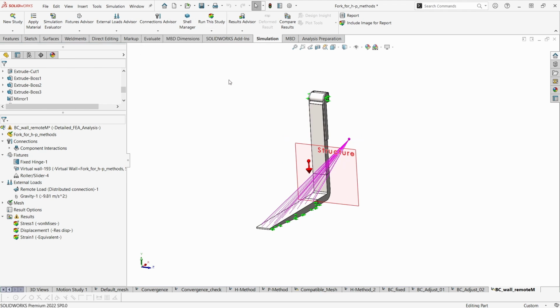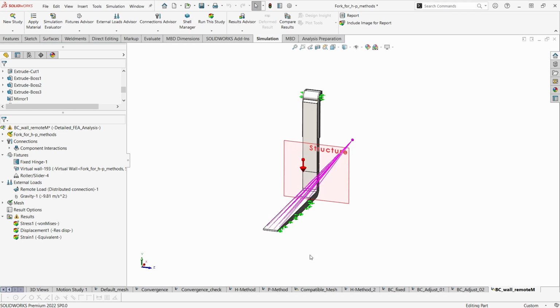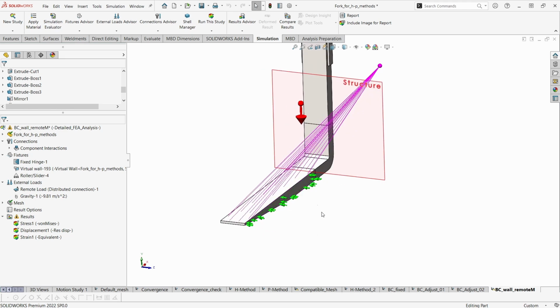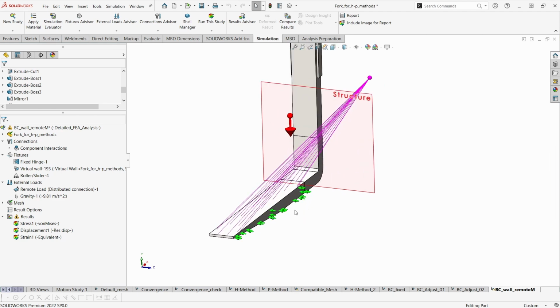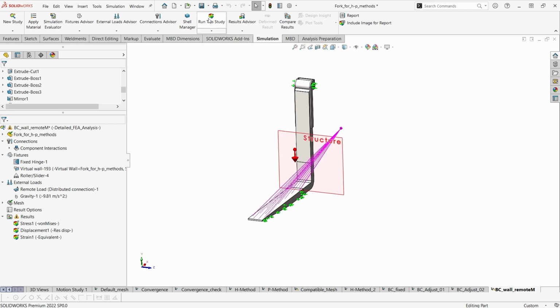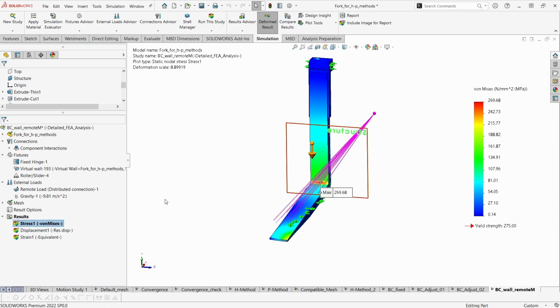It's important, before I click on run, that now we are restricting this transversal direction. But when we do this kind of calibration or adjusting our individual models just to represent what is happening in the complete structure, we need to keep the balance just to not over-constrain the simulation more than necessary. So for that reason, we are just applying the roller slider in this internal face. Okay, let's run this study. And here we have the results.